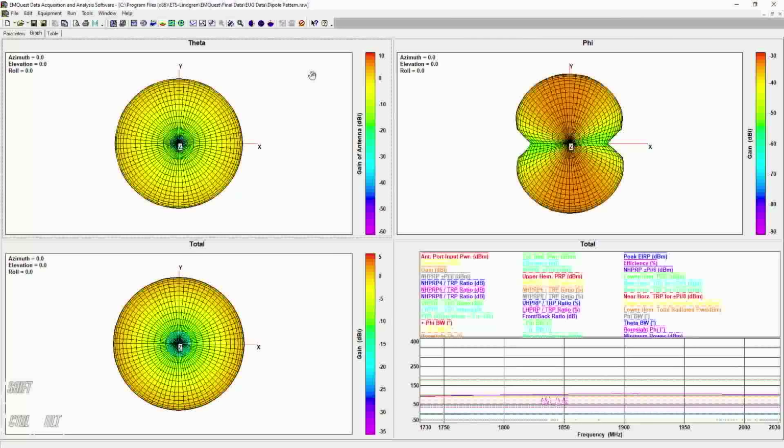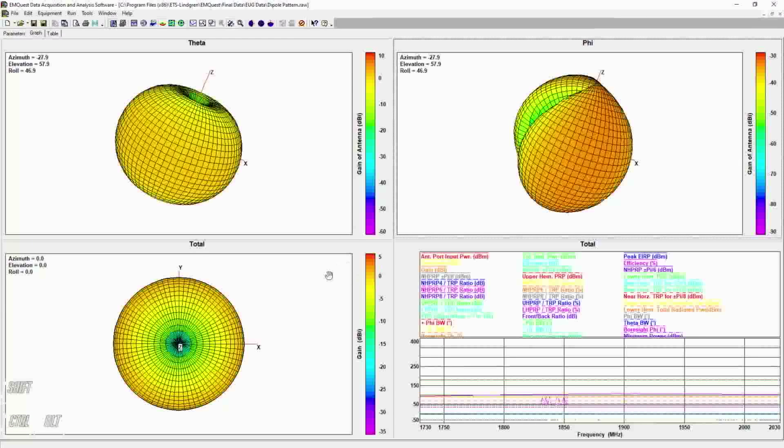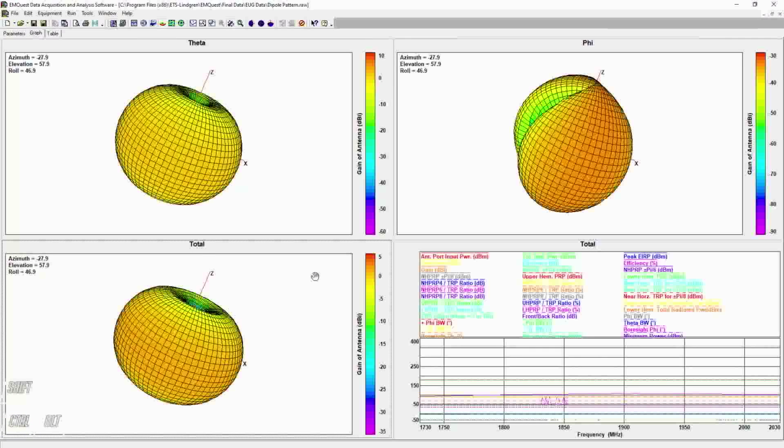Now, back to the graph settings. Let's say that I made labeling changes or other changes, or maybe I oriented things and I want my other graphs to get that information on them. If I copy it, I'm copying, of course, to the clipboard that I can use externally, but internal to EMQuest, it's copying the graph settings. So I can click on another graph and apply those graph settings by just doing a Control-V, by pasting onto the graph. And so that's a very useful tool without having to link the graphs. If I want a certain view of things, I can get that view by simply dragging that as needed.